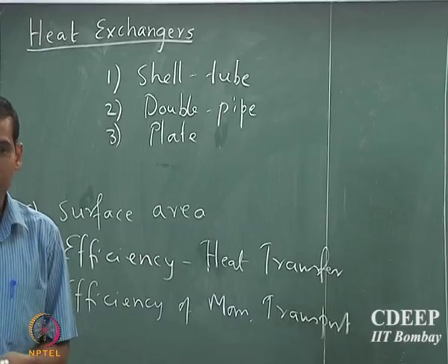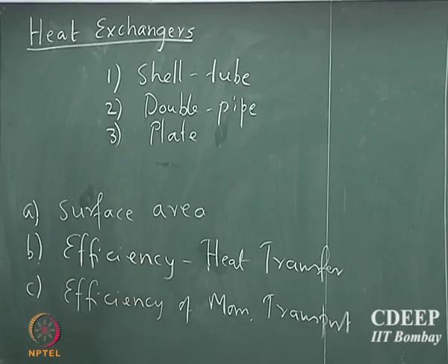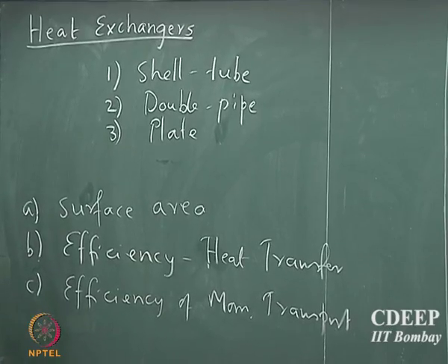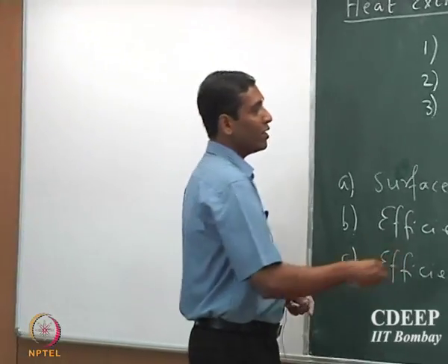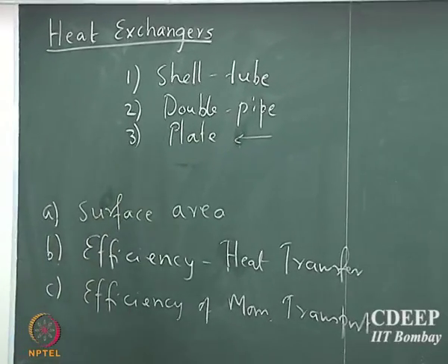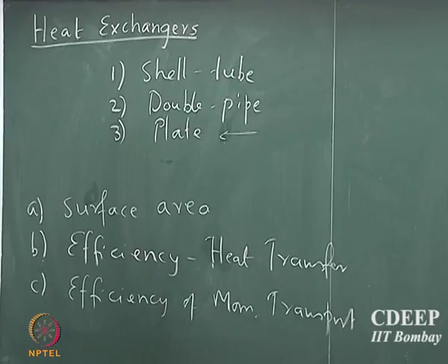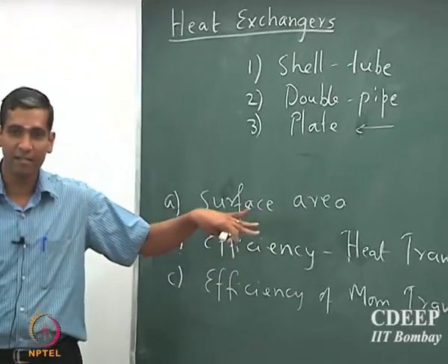That is correct, because the pumping cost is going to be minimal. If you have high pressure drop, so if you want to pump a viscous fluid, you would never want to do it in a plate heat exchanger. Well, actually, I'll sketch how these plate heat exchangers and parallel plate heat exchangers look.